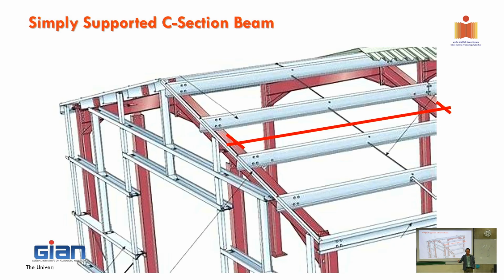This is a little bit of a long term. Okay. So the more you put that one here, the better you increase the flexural torsional buckling capacity. So sheathing is connected to the member. Yes. Where it is stopped and is restrained. That is a little bit more complicated to design, but in this case, we're looking at upward.